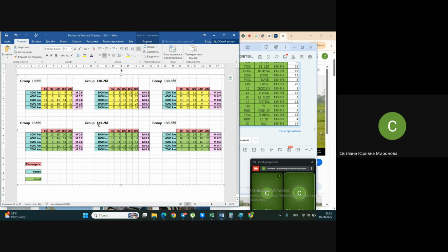Or on the contrary, if you see that you have prototypes of appropriate range, but the number of people is a little bit less or more than you need, it's the same decision. It means that in order to design your very own, you need to increase the relative weight of payload and reduce the other relative weights respectively, except the weight of crew, of course.